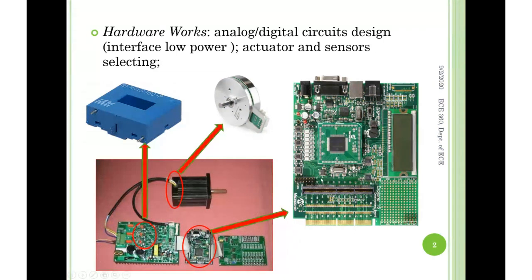You see these male pins; JTAG connects to the debugger. Then you have a power supply, maybe 9 volts or 12 volts. The controller board itself may have an LCD display, which is very helpful too. And here you have a small space for vector circuit design, where you can wire jumpers.